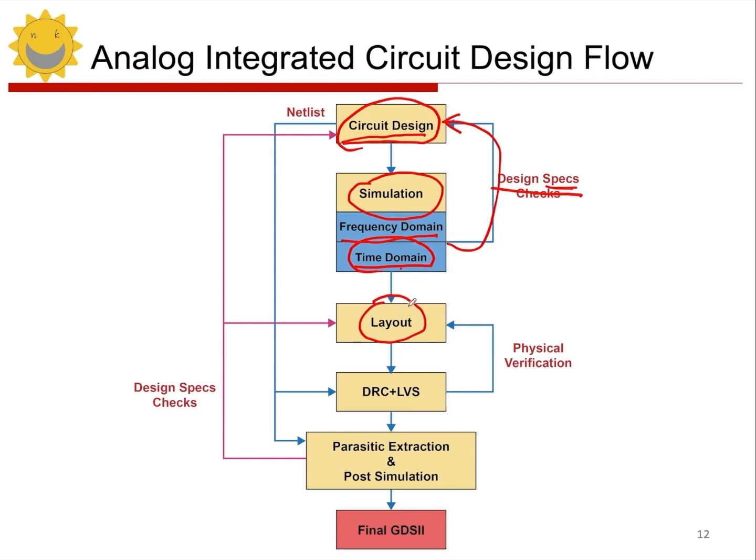After passing, perform parasitic extraction. This involves extracting parasitic info from layout to schematic. After initial schematic, a netlist is generated. This netlist is for LVS and post-simulation, incorporating parasitic parameters. Then netlist generates a post-layout netlist reflecting parasitic info. Then perform post-simulation. If post-simulation passes, circuit is reliable. If it fails, check layout issues. If layout is problematic, modify it.